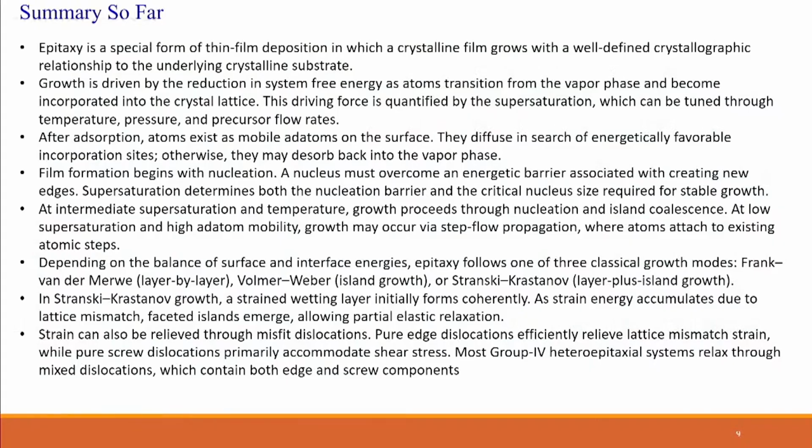Epitaxy is a special form of thin film deposition where a crystallographic order is maintained. The driving force is the lowering of free energy of the system when an atom goes from a vapor phase and forms strong covalent bonds in a solid phase. An atom is metastable on the surface. It needs to diffuse and find a nucleation site, or else it dissolves.